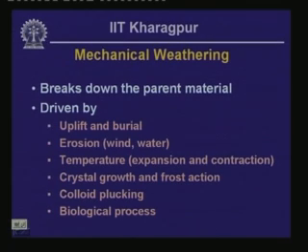Crystal growth and frost action can split a rock mass, because the volume of the secondary crystal that develops in that process is different from the original solid, and that splitting of rock mass can also give rise to mechanical weathering.